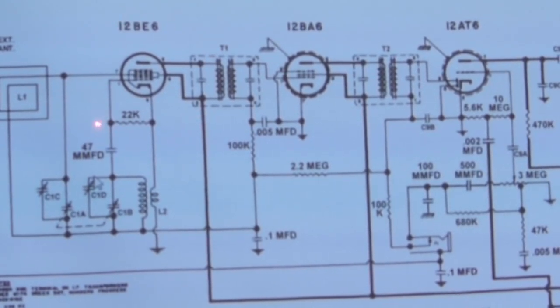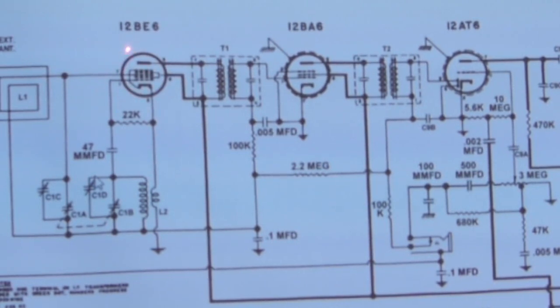When audio circuits misbehave, there is some heterodyning that takes place in them, and that's called intermodulation distortion. And that's something that you want to avoid and get rid of. But anyway, we're not going to spend too much time on that. We're going to go in here to our first IF, and as already pointed out, the IF transformers are working on a 1-to-1 ratio between primary and secondary, and they're tuned to 455 kilohertz, as has already been adequately demonstrated. And so the 455 kilohertz, which is then present, especially here, is fed into the first IF amplifier.